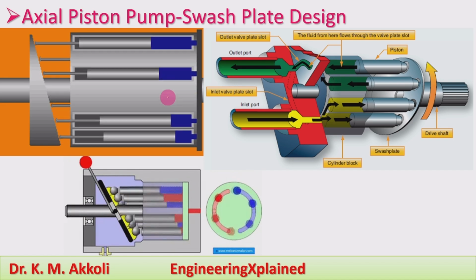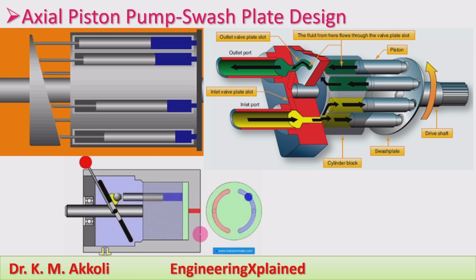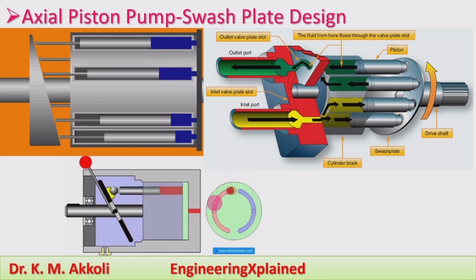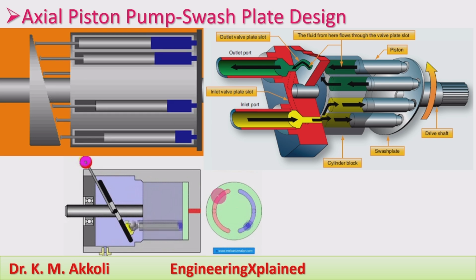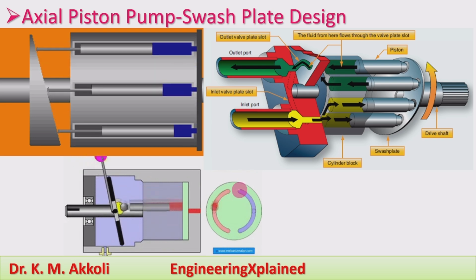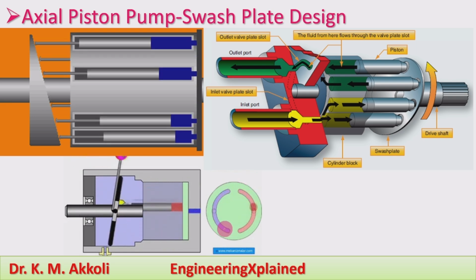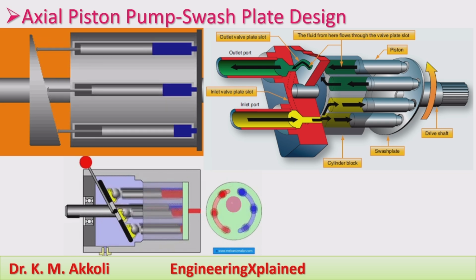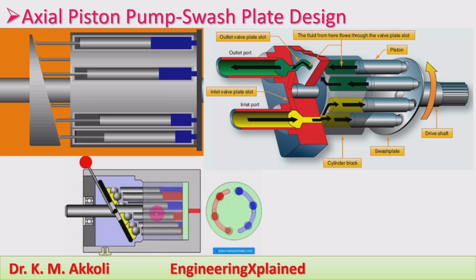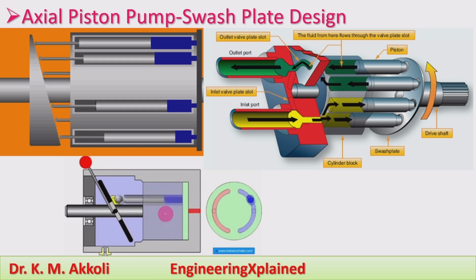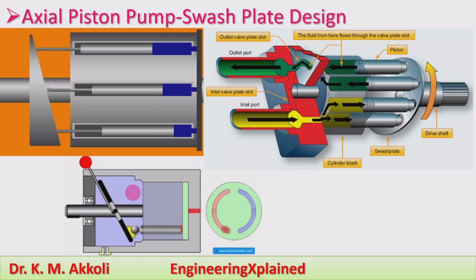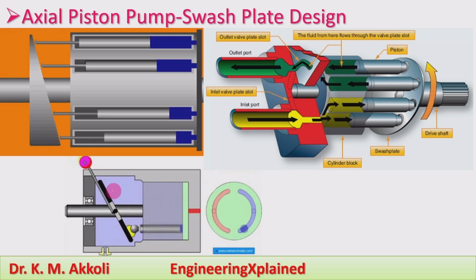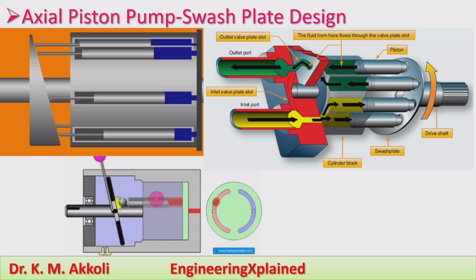And again, this can be seen here. We can see, whenever this is rotating, the piston in the swash plate, how the slots are provided. With the rotation here, the suction will be taking place at this position, and discharge will be replacing that one. With the number of pistons here, one cylinder is in suction while one cylinder is in discharge continuously, and the angle of this swash plate can be varied in order to vary the flow rate.